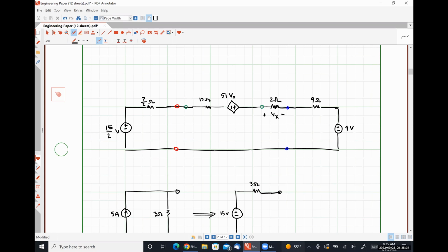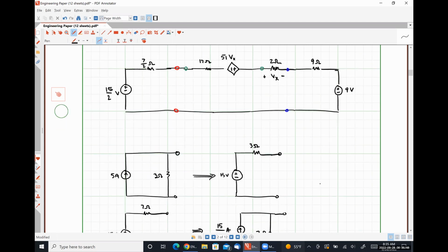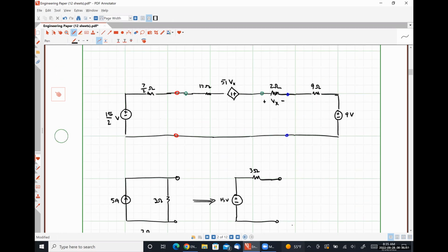All right, so you may be asking yourself why and/or how this might be practically useful, which is a pretty reasonable thing to ask yourself, okay? So if we had a very convoluted circuit and we were interested in determining how much power is delivered to a single resistor or something like that, we could use a practical voltage source equivalent circuit or a practical current source equivalent circuit to effectively do our power analysis on that much smaller scale circuit.